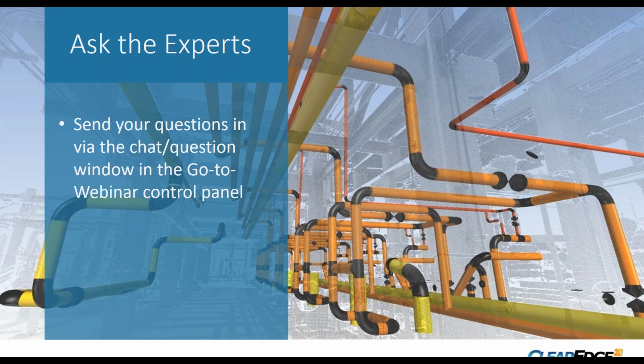So, like with any software that works with laser scans, the quality of the laser scan data absolutely impacts what we're able to do from a software and an algorithm standpoint. That being said, we've had very good results with things like ductwork, duct with duct wrap, black sprinkler pipe, because fortunately the errors that the scanner gets usually are relatively statistically spread out, and so you end up with a relatively good idea of where that piece of geometry actually is installed. You just probably wouldn't want to go to a subcontractor and yell at them if it said it was 1.01 inches out if it's a big shiny object, because the data obviously is not 0.01 inch accurate.